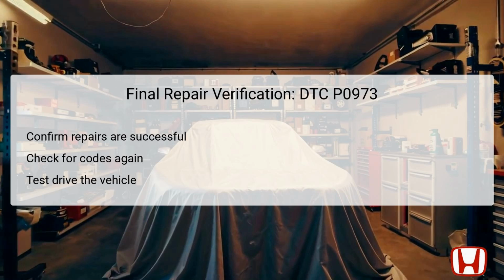Once repairs related to DTC P0973 have been executed, it is critical to proceed with a final verification step. This process begins by confirming that the repairs made have successfully resolved the issue, which you can validate by checking for any error codes once more using the HDS.